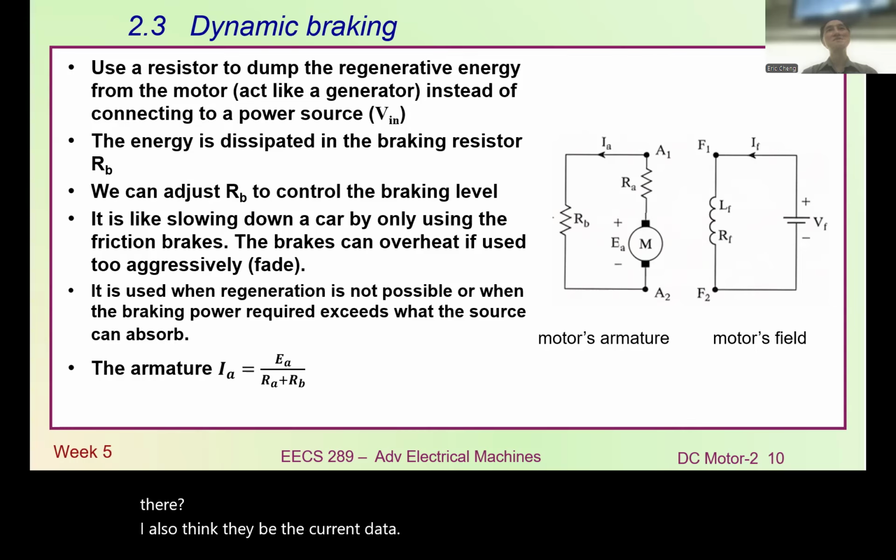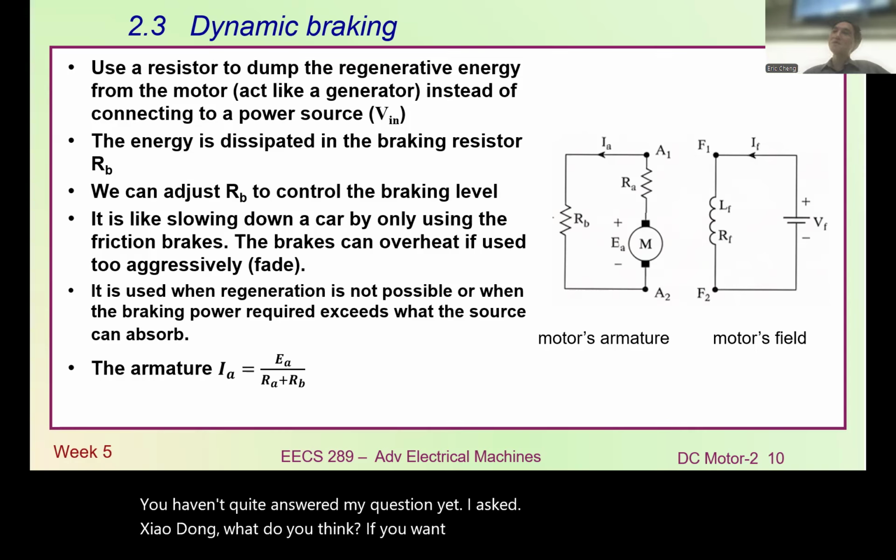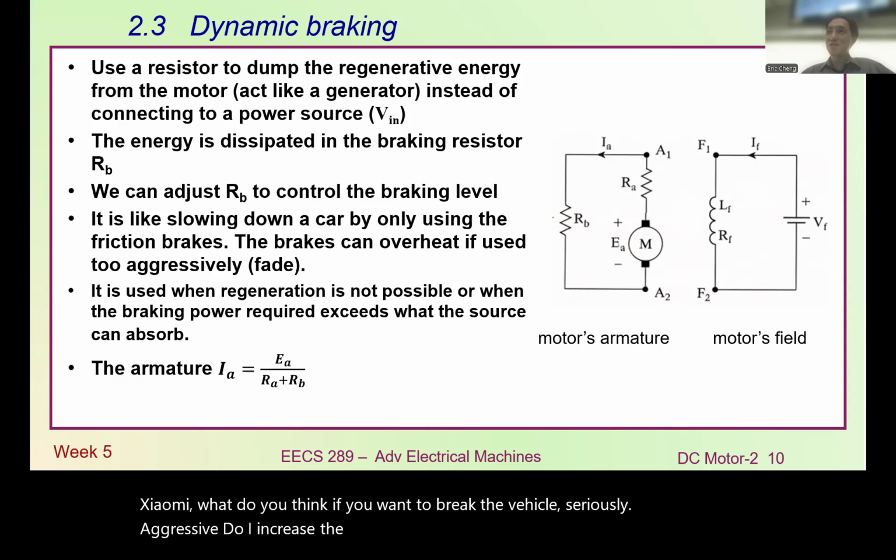You haven't quite answered my question yet. I asked Xiaodong, what do you think? If you want to brake the vehicle seriously, aggressively, do I increase the RB resistance or decrease the RB resistance? Decrease the RB. Yeah, okay. Think about it.